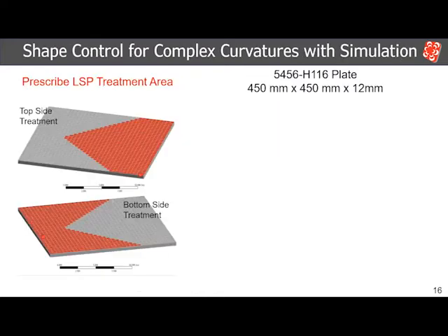So a little bit on our finite element modeling process. For peen forming, our tendency is to use what's called the eigenstrain process of modeling. That'll be covered later, but essentially how it works on the slide shown here, the red areas represent where we are applying laser peening to our component.